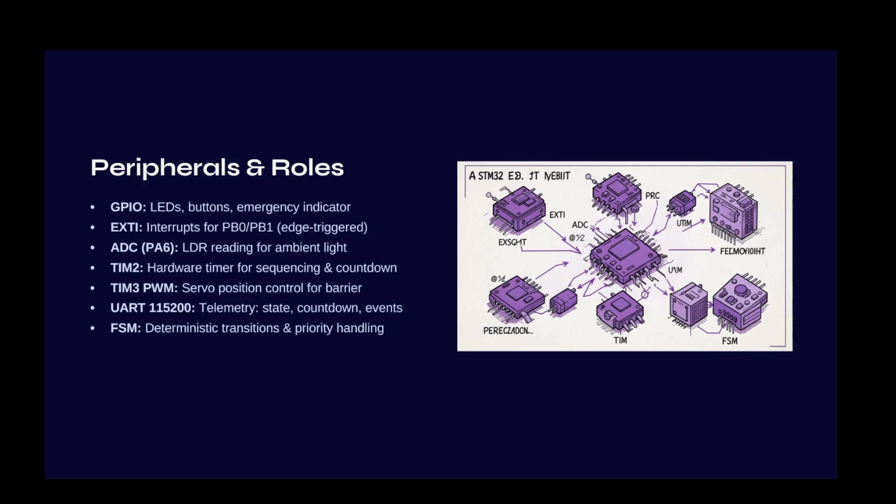PWM. PWM stands for Pulse Width Modulation. I learned how PWM controls the servo motor. By changing the duty cycle, we can rotate the servo motor and open or close the traffic barrier.